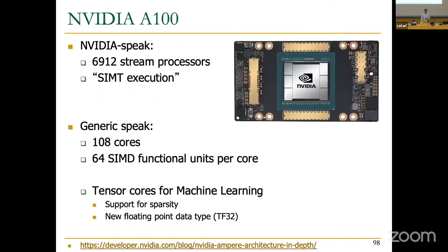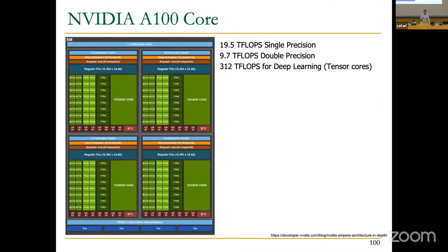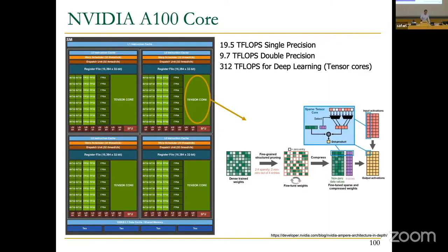Okay, let me show you where we're getting towards. This is A100. This is still not the state of the art, and it's increased even more. You can see that there are new data types being added, tensor data types, floating point data types, and then support for sparsity, because in machine learning you operate on many matrices that have zero values. So they actually have mechanisms to not operate on zero values. That's one way of accelerating machine learning: ignore zeros as much as possible because you have a lot of zeros in some of these computations. So this looks much bigger, as you can see, and the numbers have all increased. It was 125 teraflops, now it's 312, for example, for deep learning. And the tensor core is beefier, and also the GPU is beefier.